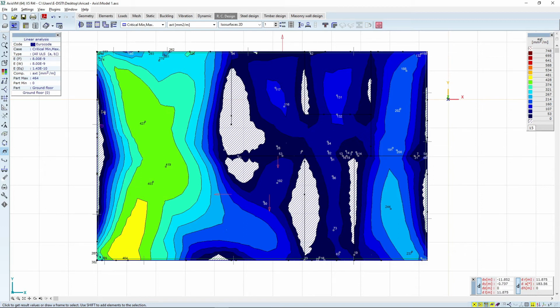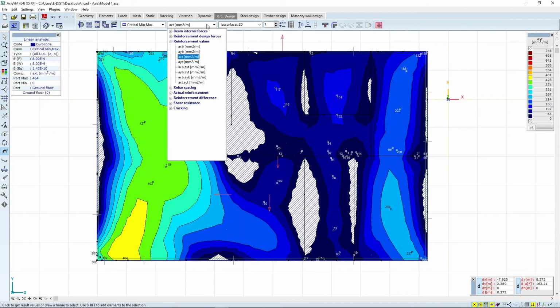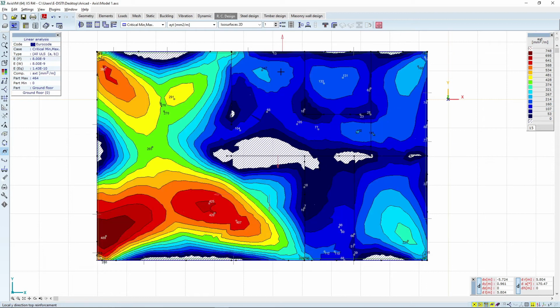You can change that very quickly at this option when you are reinforcing parameters, and you can change it from 20 to, let's say, 30, which is a bit more standard size slab, and it will reduce the required reinforcement. So this is top reinforcement for the bottom slab in X direction and top reinforcement for the Y direction. So it is all around 420, 500 here where we have a bigger opening.